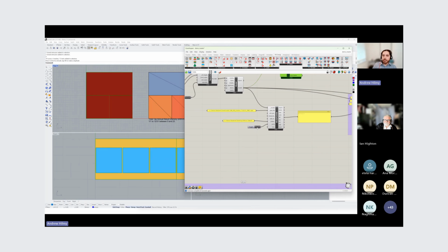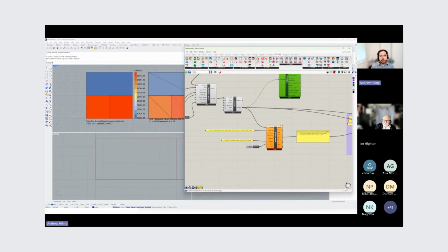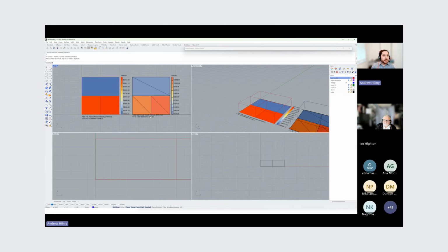what it will do is it will again do the same thing. It's changed the window, so it will re-import the IDF file. It will recreate the building simulator file. It will re-simulate, and then it will extract the results. It will create that header so that the Honeybee color by rooms object understands how to present the data, and then we should see it appear back here in the plan. So I think that's finished. And if I turn off preview, lock the solver so I don't slow it down by accident. So yeah, here we can see the result with the much larger windows. So you can see the cooling demand is bigger.